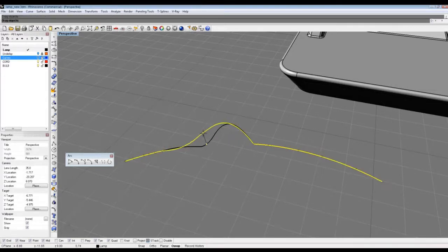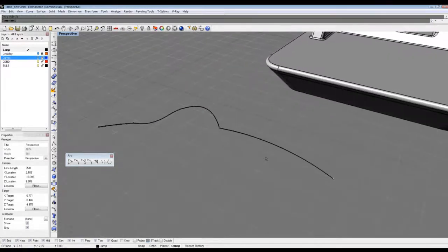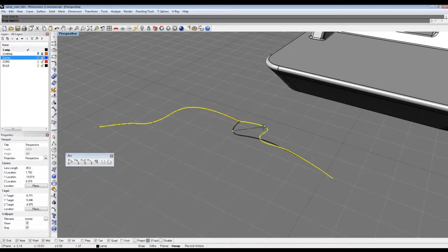One thing I would say, and this was a great topic that came in on a webinar I was listening to on T-splines, was to make sure that you really need the control point or the edit point. A lot of times people think that by putting in a whole bunch of edit points or control points, it's going to help you define what you're trying to show. Oftentimes you only need like 3 or 4 control points on a curve to really be able to describe it, unless you're doing something that's highly organic and has a whole bunch of little kinks and puckers. The closer your points are together, the sharper your form is going to be, and the further away they are, the more of a broad, smoother shape you're going to get.